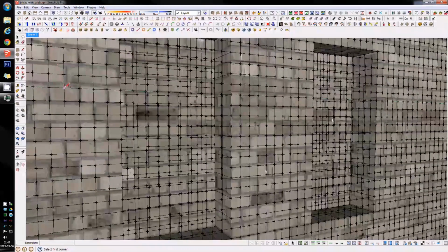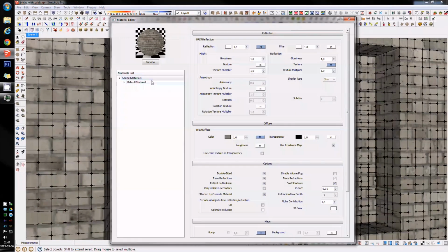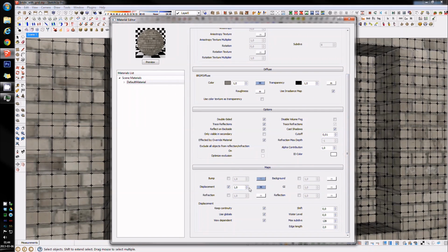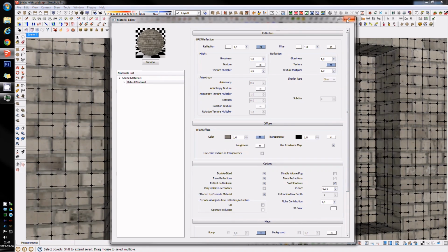If you are rendering large areas of displacement, the dynamic memory parameter is quite important, but in combination with 4 GB memory, there's not much we can do. I will show you an example. If you are rendering large surfaces, what you need to do is split them into smaller ones. This is because the performance drops dramatically when it comes to the dynamic allocation of memory to each thread of your processor when you're rendering close-ups to the surface of displacement.